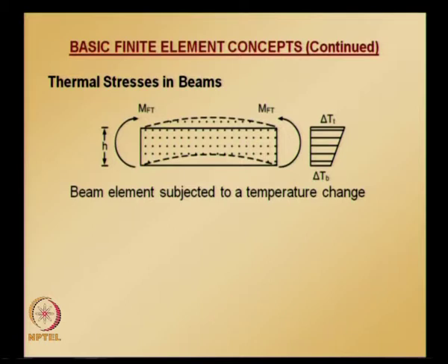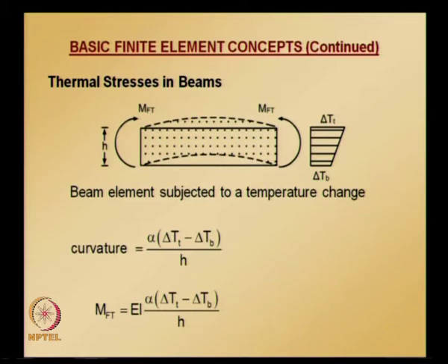And when we apply end constraints for this kind of element, fixed end moments are going to be developed, which are indicated there as MFT. And when there is a change in the temperature of the top surface and bottom surface, the curvature that this beam element is going to experience is given by this, and once we know the curvature, we know the relation between the curvature and bending moment.